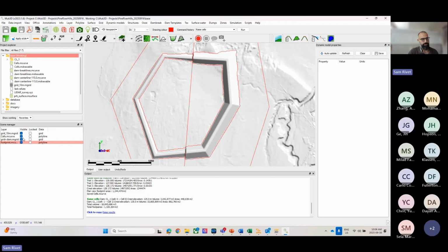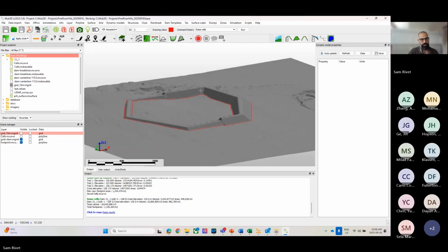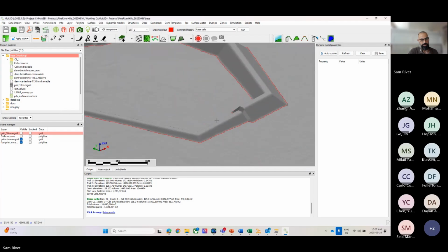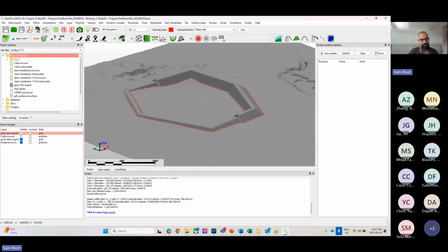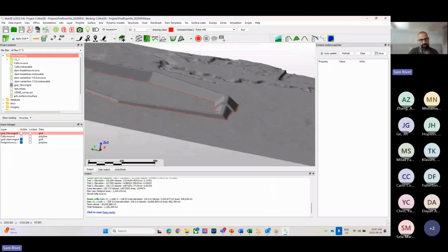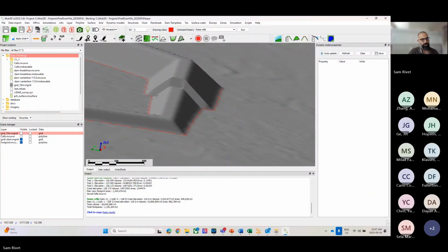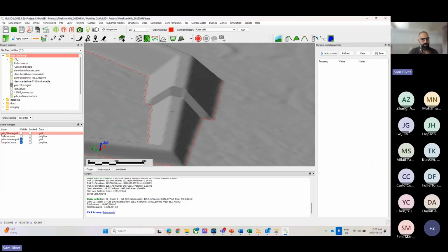Let's take a look at this. I'm going to turn my cell layer off, my grid 10, and take a look at this new merge grid that's been created. Okay, so you can see here, I've applied the template. You can see it's the center line template, same center line, but different upstream and downstream toes depending on the elevation that we're at. And one side's here at 125 and the other side's at 135.